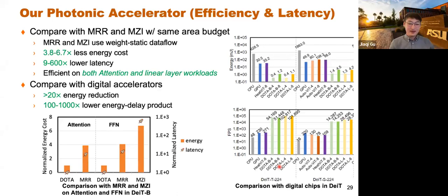for that? Yeah, definitely. There's no winning device, because different companies and research groups focus on ring, MZI, or even in-memory computing, right? Phase change material, encoding in the Fourier domain. There's no winning solution. The better solution is to go to a hybrid one, right? For example, MZI is probably for static computation, and our design for dynamic computation. And rings for ultra-compact designs, because the size of a ring is much smaller. If you have a very stringent chip area budget, you cannot use MZI. You have to use ring. So based on different constraints, you have to use different devices.